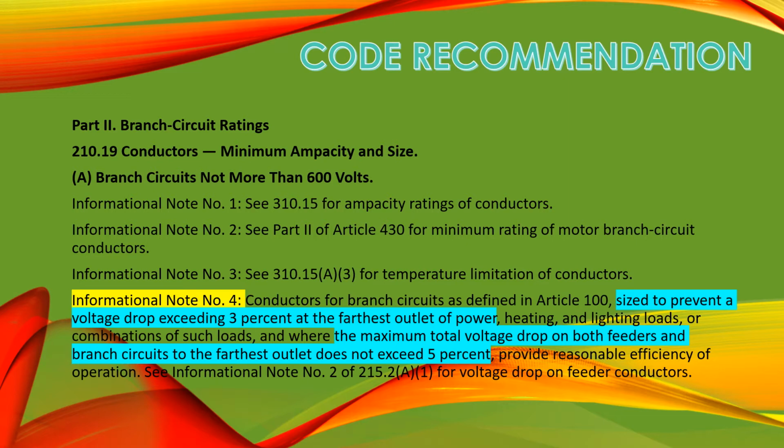That is one example why this code says it will provide reasonable efficiency of operation. And of course, if you put a low voltage to a lamp with a higher rated voltage, when you decrease the voltage more, it will just flicker. It will not give the correct or expected output.